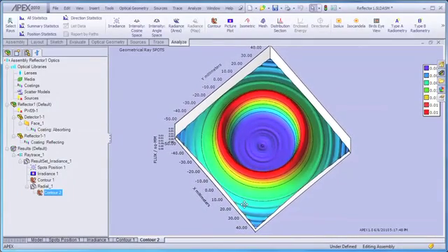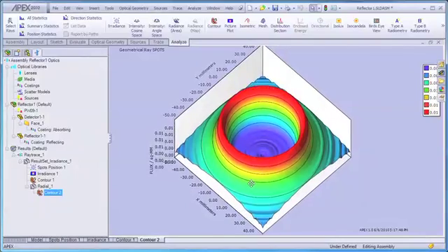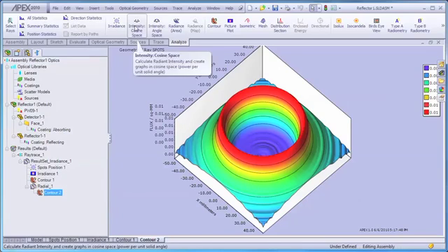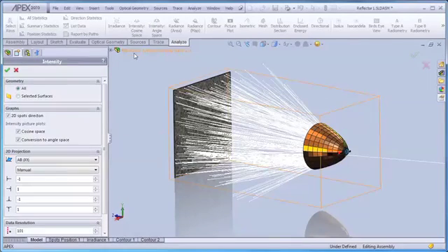It also implies that we might not need to trace nearly as many rays for a symmetric system as we might for other systems. Now that we've viewed the irradiance distribution on our detector surface, we can immediately calculate the far field intensity, in this case for all rays in the system, including rays at the detector as well as rays coming from the faceted reflector which miss the detector surface.